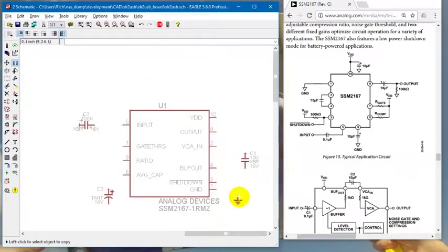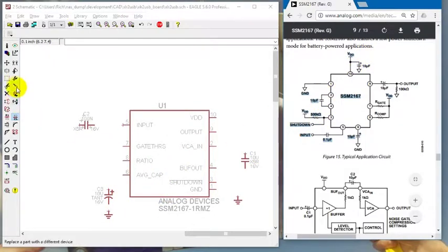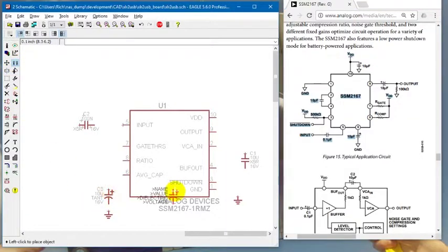I can also, if I don't feel like typing the word add all the time and running into that filter thing that happens, I can add my stuff that way. What else we got on here? Another 10 microfarads. Oh, let's set the value of this so that that's done. Okay, 10U that way. And the same 10U that I needed for my average cap on pin 6 is the same one I'm going to use on pin 10 as VDD. So that means it's just an easy copy.